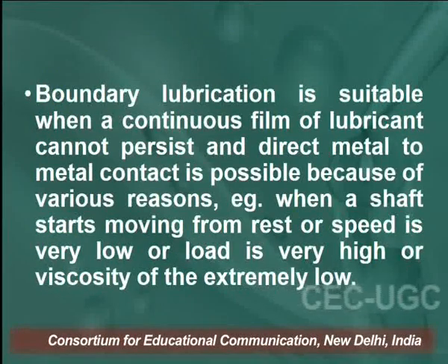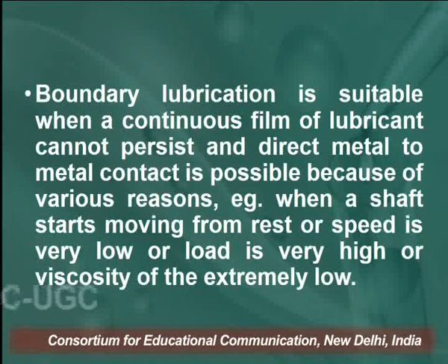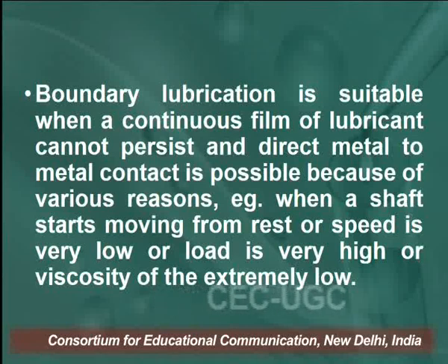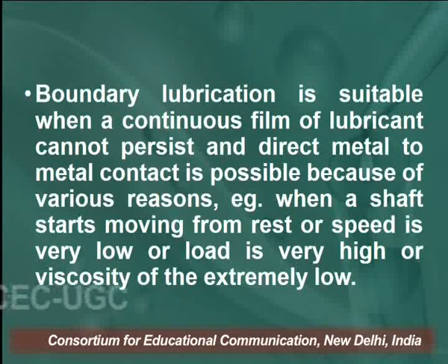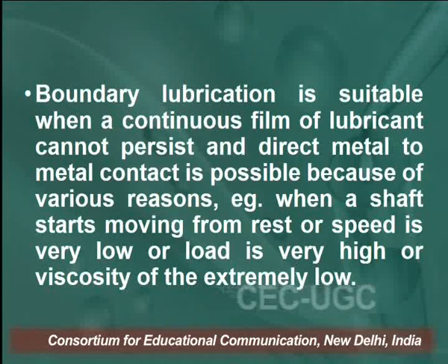Boundary lubrication is suitable when a continuous film of lubricant cannot persist and direct metal to metal contact is possible because of various reasons. For example, when a shaft starts moving from rest, or speed is very low and load is very high, or viscosity is extremely low.